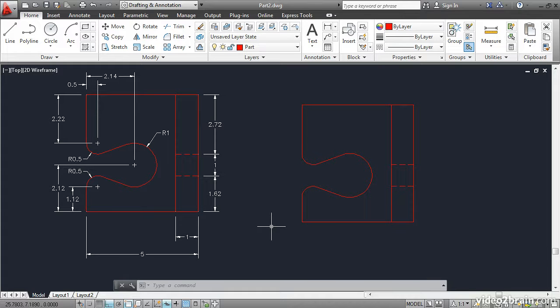So you have learned how to call for object snaps one at a time using the Shift right-click menu and by typing three-letter abbreviations on the keyboard. You have also learned how to use running object snap modes, which leave your chosen object snaps on continuously, saving you time. In addition, you have completed a complex drawing and used a few modification tools in the process.